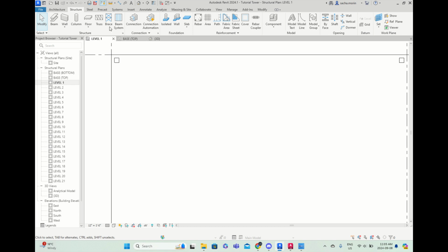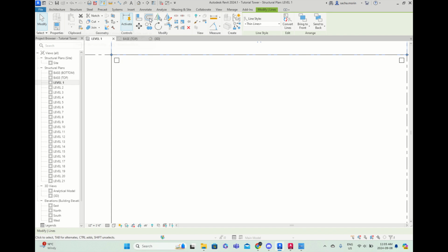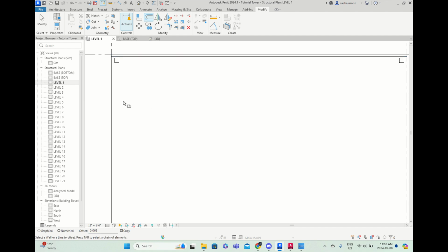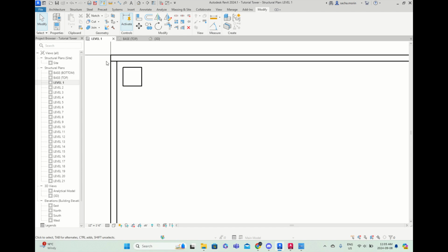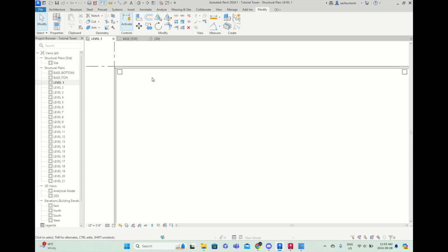Therefore, the center of them will be at 1/16. So we can go back to this offset tool that we know and love, input 1/16, click enter, and make that offset for both. And there are the middle of our beams that we can already define right now.